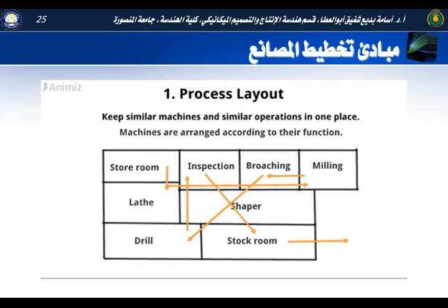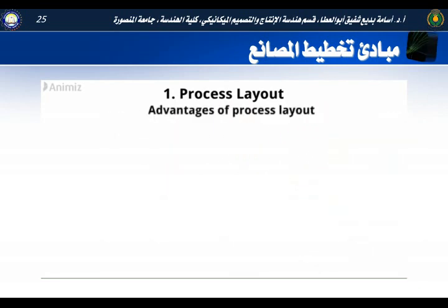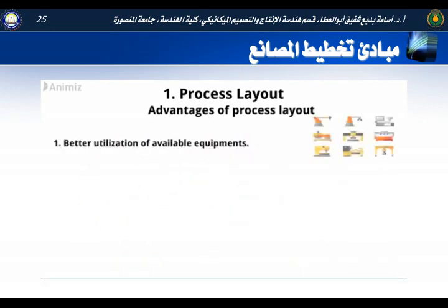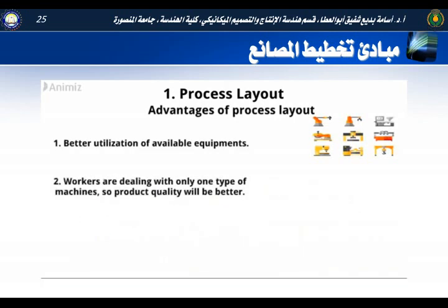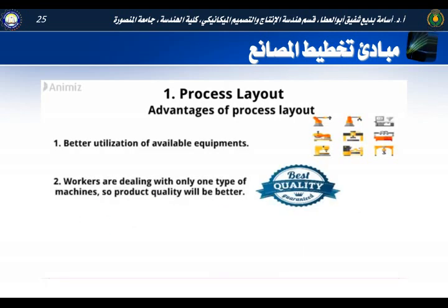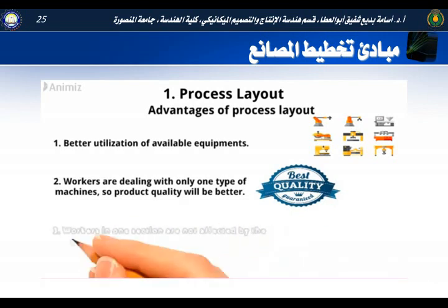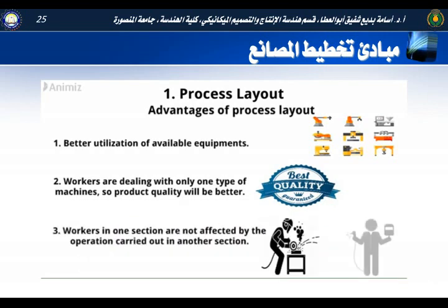What are the advantages of process layout? 1. Better utilization of available equipment. 2. Workers are dealing with only one type of machine, so product quality will be better. 3. Workers in one section are not affected by the operation carried out in another section.